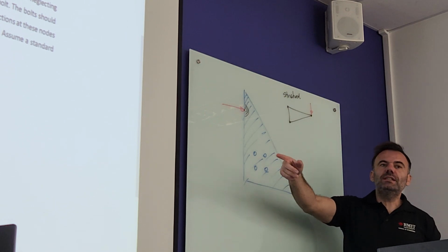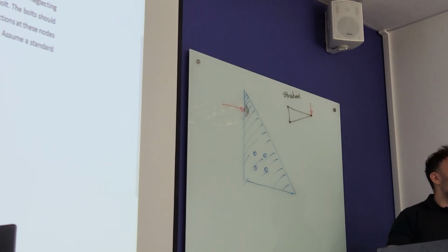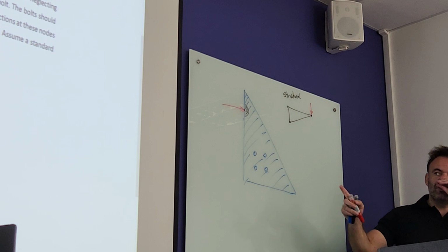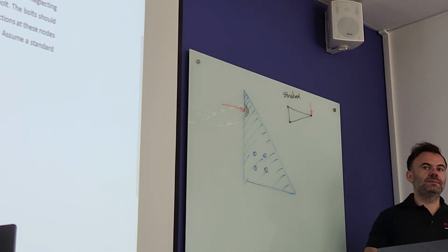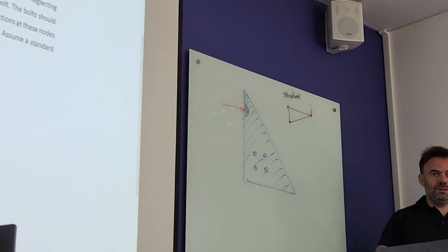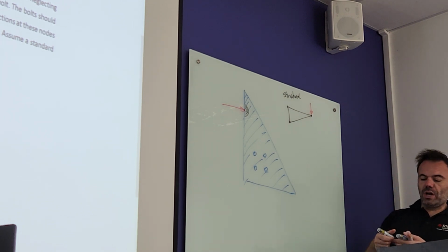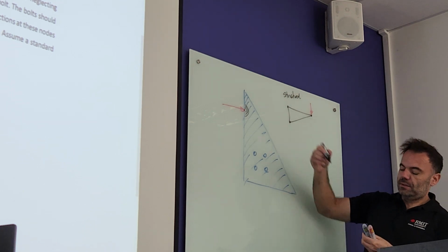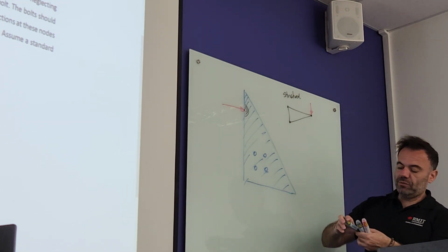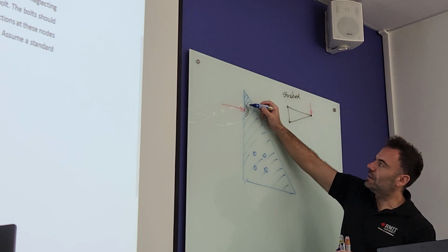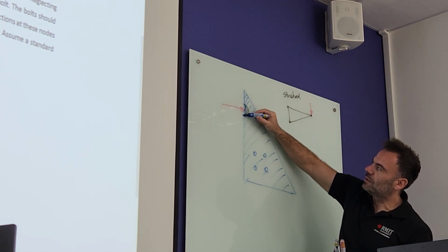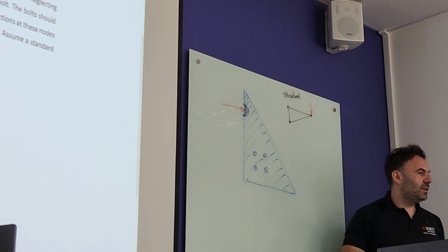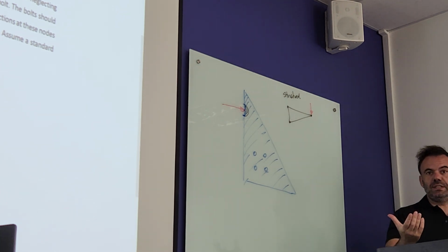What would be alternatives to this? What would be an alternative approach rather than using a point load? Something that's more realistic. Pressure, yeah. So if we apply load on a bigger region, let's say we use that patch and apply pressure, that will be more realistic.